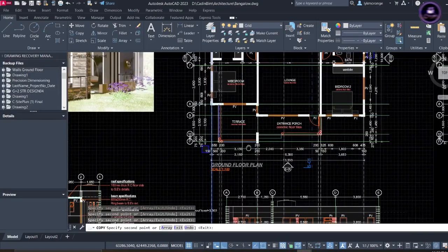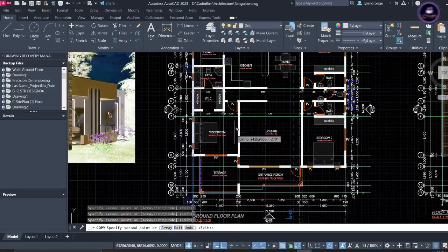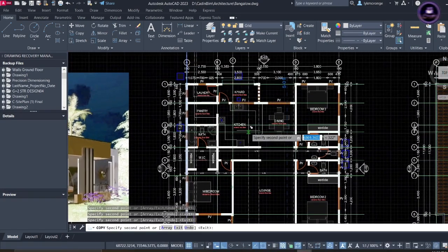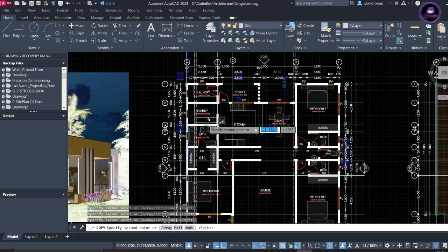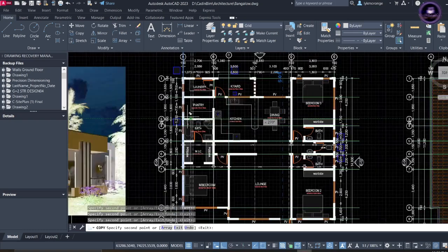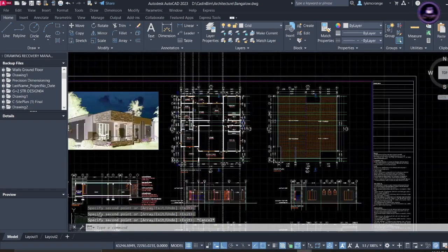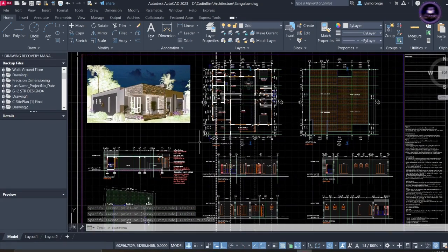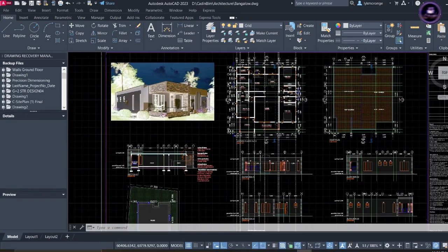What else do we need? Ensure that every place that you have a wall, you add your axis. That's the rule here. It's guiding us, and that axis must bisect our wall at the center. But for me, I'm just making an assumption that these existing grids are bisecting the center lines of these walls. So with that, I'll now proceed to draw the horizontal axis, the horizontal grid.